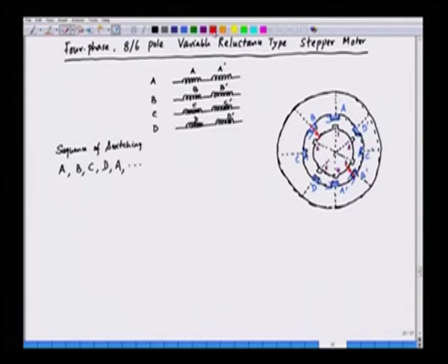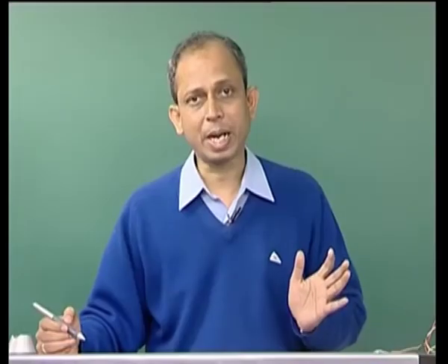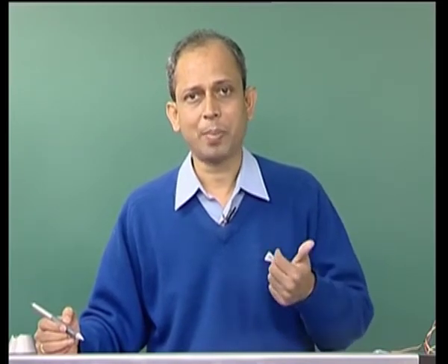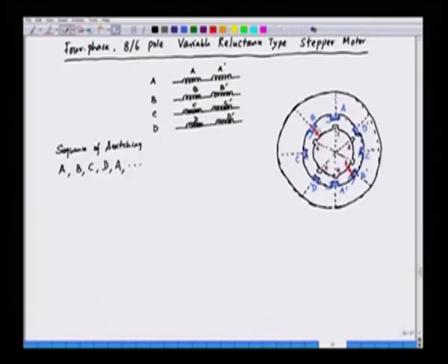How does the rotor respond? The rotor rotates in such a direction so as to align its pole along the MMF. The rotor poles closest to this excited phase are 6 and 3. So, 6 will be moving under phase B and 3 will be moving under B prime. So, what is that angle? That angle can be determined if we extend this and try to calculate it.